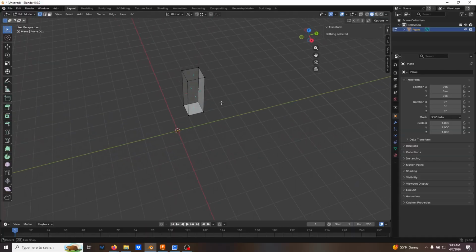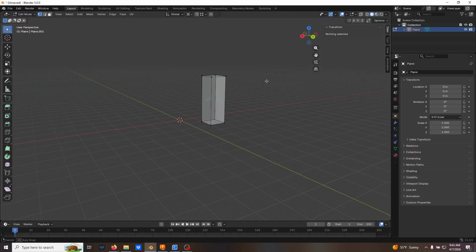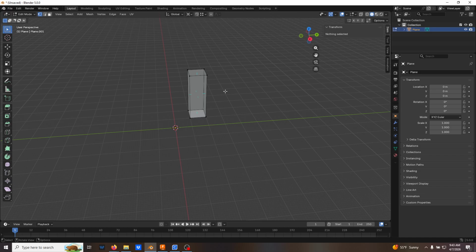So again, just going back to functionality that I want to highlight in Blender, this is a good way to check and proof your STL files, because one of the most common problems with STLs when you're trying to put them in a slicer for 3D printing is flipped faces. So I just want to say that this is a way that you can mess with that.